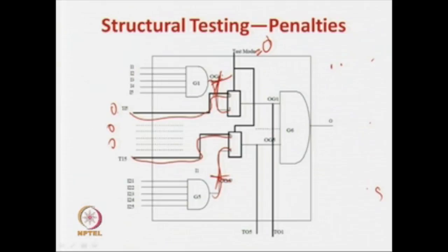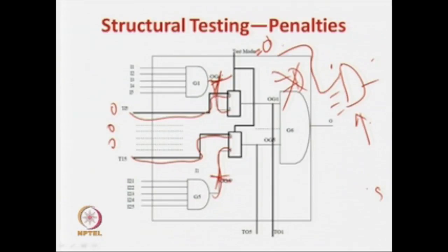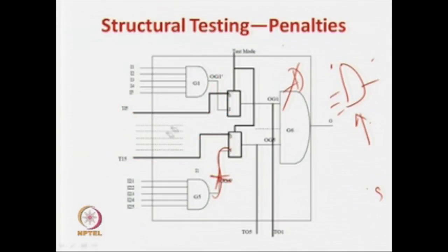So, now what we have done. There was this gate and this is the line. So, this is the internal gate, some other gate which is driving it. Now, to apply a test pattern, because our idea is to test this gate individually rather than the whole circuit, what do we have to do? Some other gate is driving this gate. So, in the test mode somehow we have to make this gate unable to drive this, and there should be some extra pin outs which can now drive this gate, so that you can apply test patterns as you like and test this gate individually. This is possible in this case, or in all cases, by using a 2:1 multiplexer. So, the basic architecture is something like this.